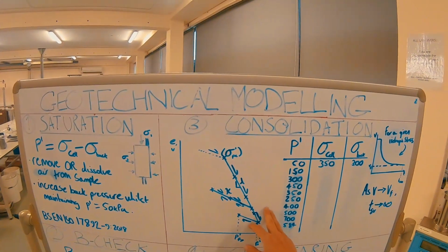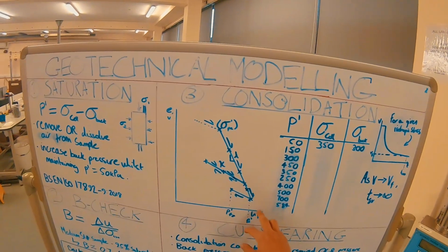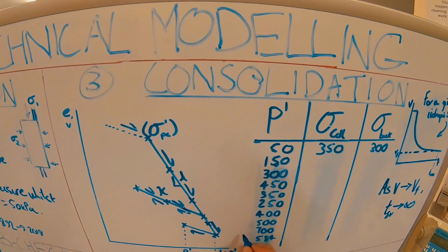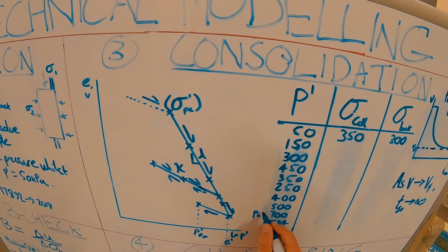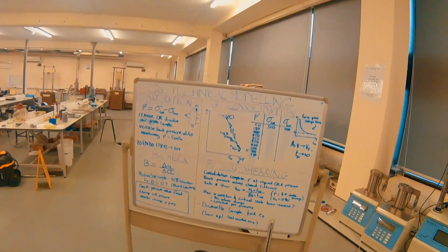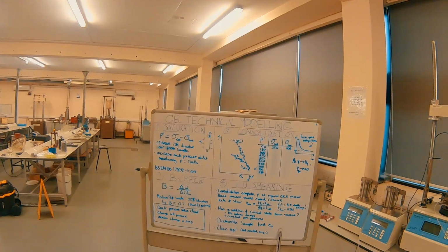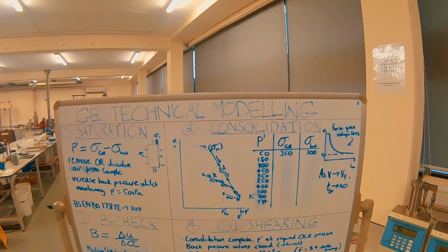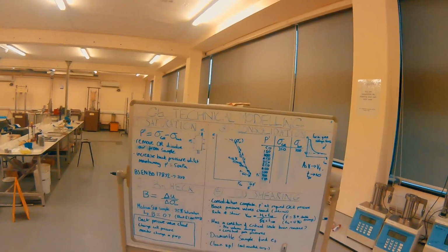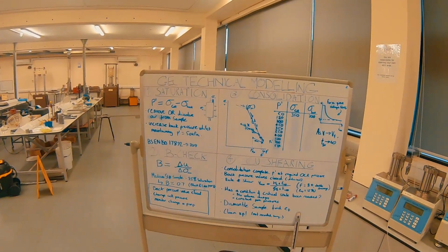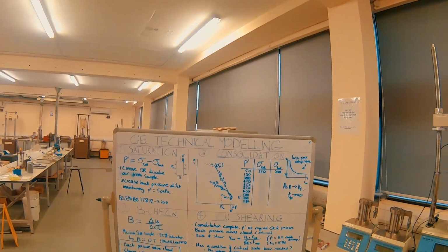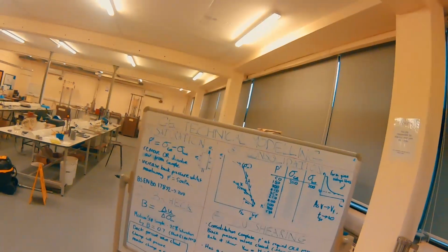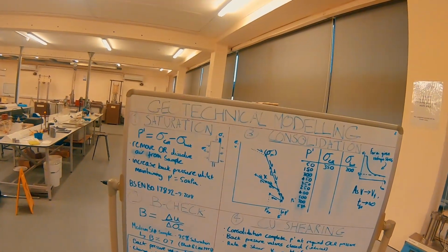After we've gone off our kappa line, we get 2 more readings of 500 and then 700, where 700 is our new P0 dash. P0 dash, of course, being the maximum isotropic stress that the sample has experienced, or the maximum stress. And so in that 700 we have, hopefully, and there have been a few bits of research conducted into this, completely destroyed the 1D-ness or the one-dimensionality of our compression in our QP space.